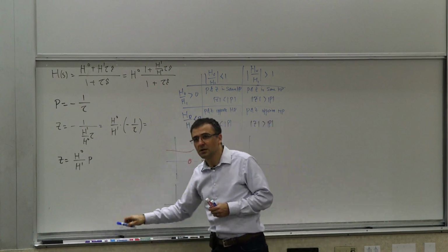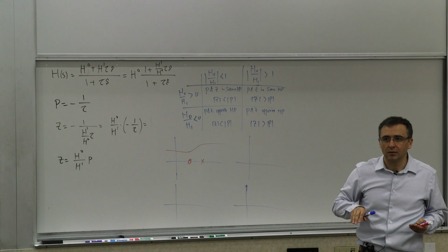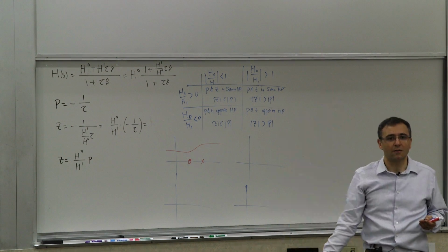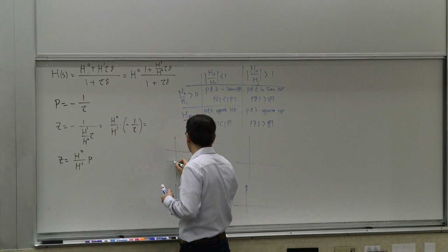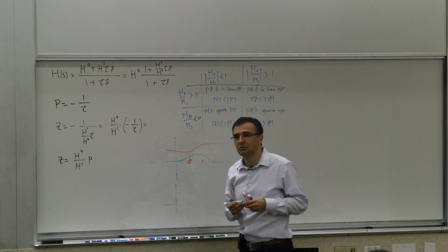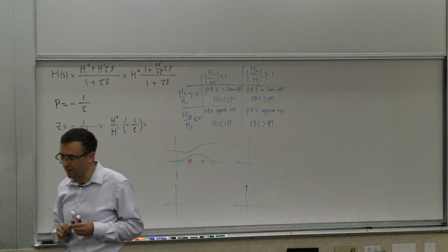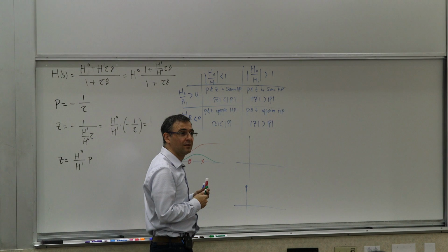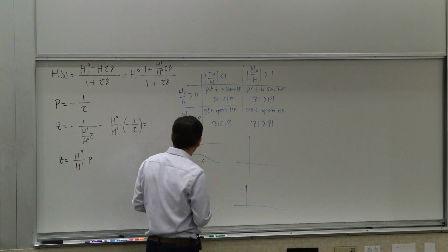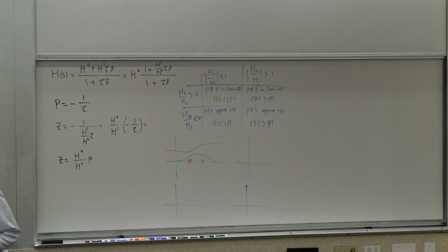And how about the phase response? The phase response of a zero gives you increasing phase, and the phase response of a pole gives you decreasing phase. So what you can expect to see from the phase response is that the phase will go up and comes down, comes positive, right? Is that correct? I think it's correct. Just double check. Yep.